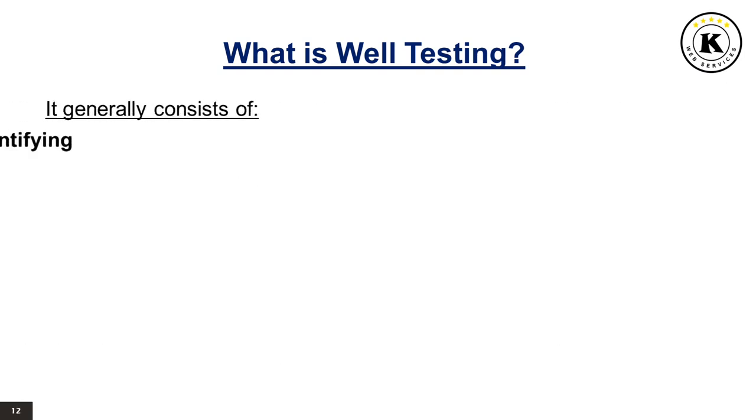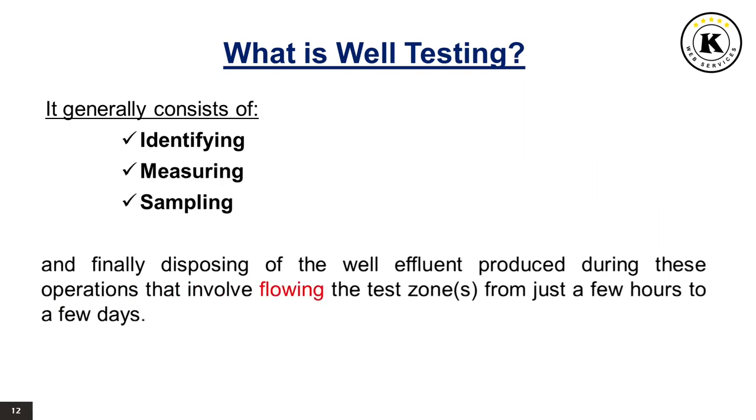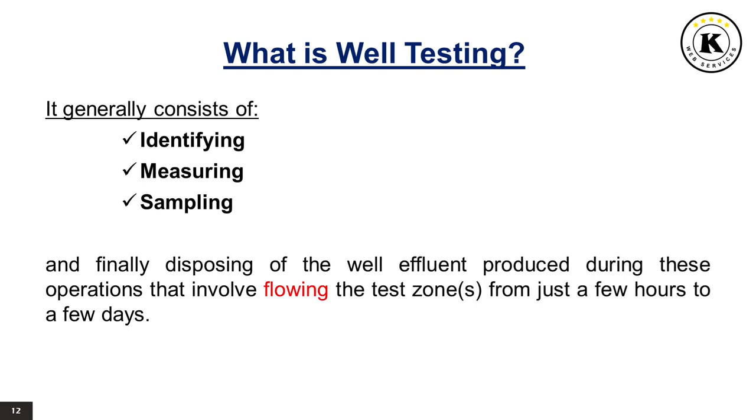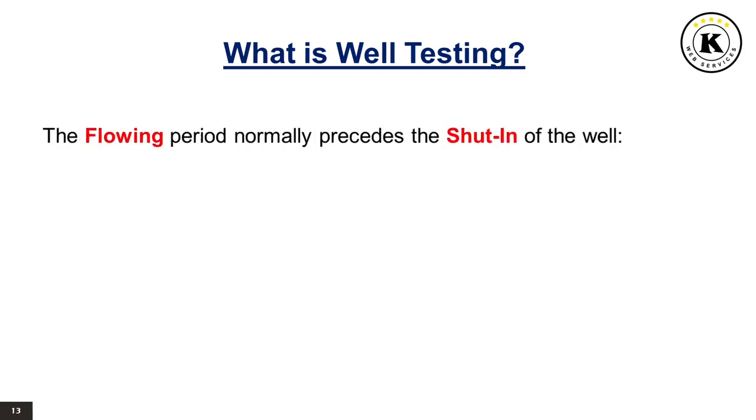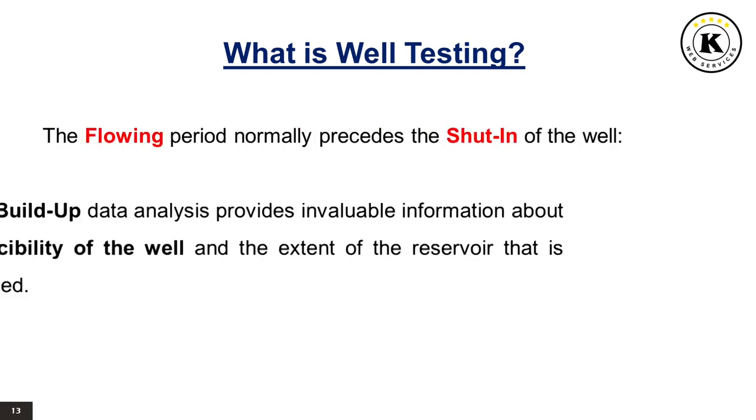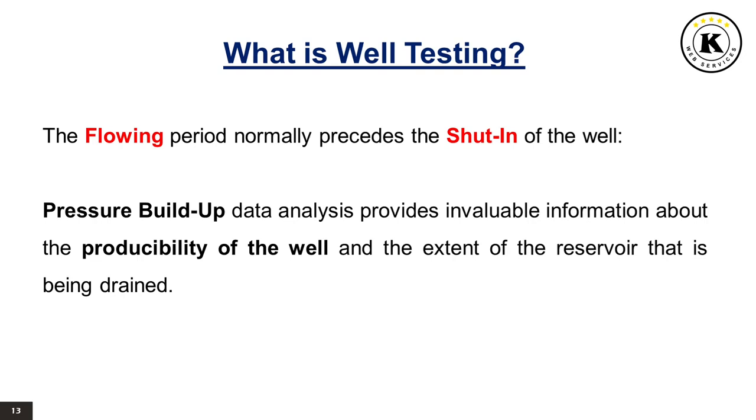It generally consists of identifying, measuring, and sampling, and finally disposing of the well effluent produced during these operations that involve flowing the test zones from just a few hours to a few days. The flowing period normally precedes the shut-in of the well. Pressure buildup data analysis provides invaluable information about the producibility of the well and the extent of the reservoir that is being drained.